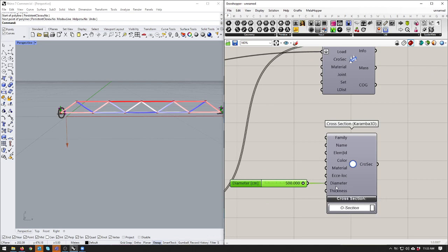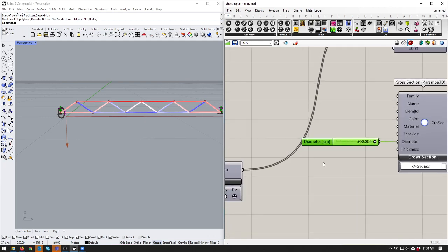Yep. So I think in millimeters normally. This is written by a German engineering firm, and they think in centimeters when they talk about their profiles. Actually, Germany's got a weird relationship with the centiliter and the centimeter. For example, if you've ever been to Germany, they have 50 cl bottles rather than 500 ml bottles and stuff like that. So just be mindful that whenever we're using any of these cross-section dimensions, we're actually needing to write them in centimeters.